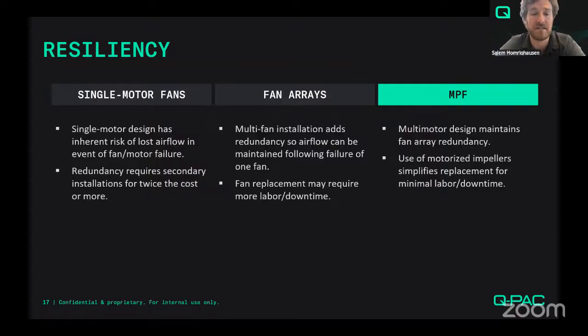And the fan arrays did solve this, right? So when you have multiple fans, if one of these direct drive plenum fans fails, the other ones can ramp up to compensate. But again, if you do lose one of these direct drive plenum fans, it may be a little bit more difficult to replace or to repair. You might have to have a gantry inside the airstream, you have to actually use a chain fall and pull it out, and that increase in labor can be cumbersome. So again, the nice thing about an MPF is that there's much less labor requirement. The product should be designed to be maintained easily, but it still will have the same redundancy or resiliency as we think of it as your fan array, just much easier to maintain.